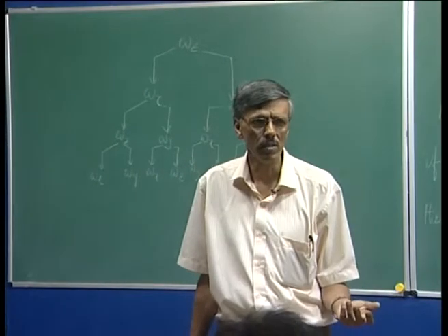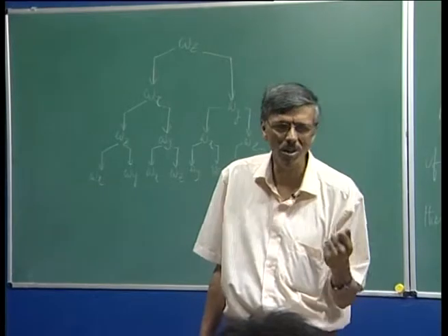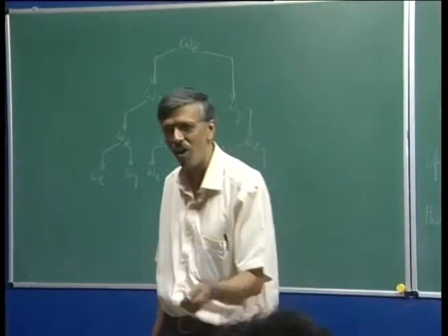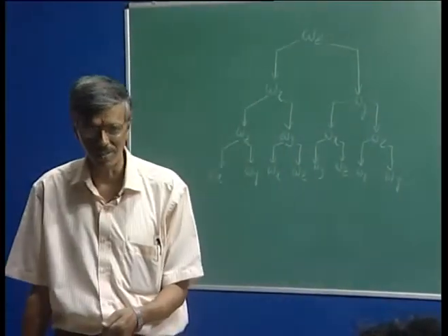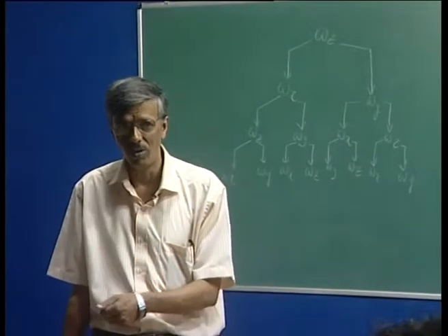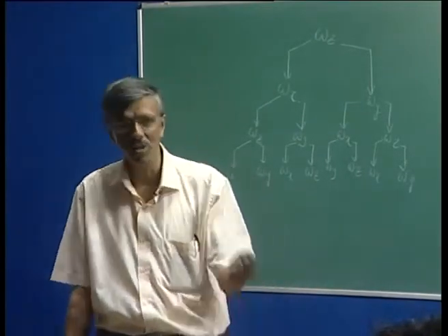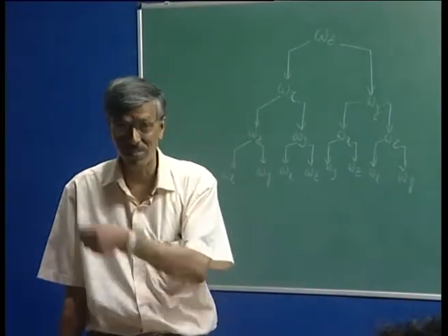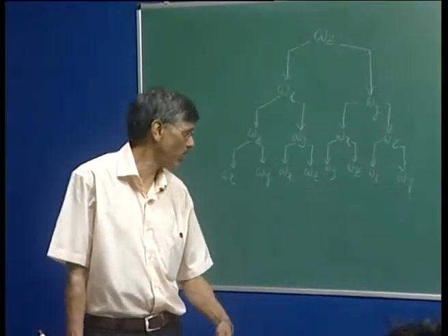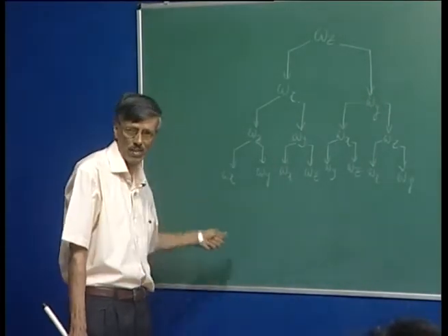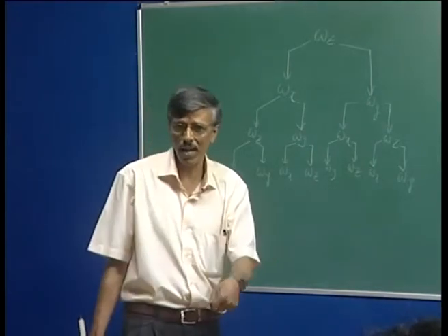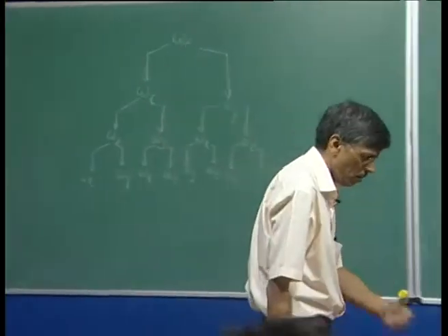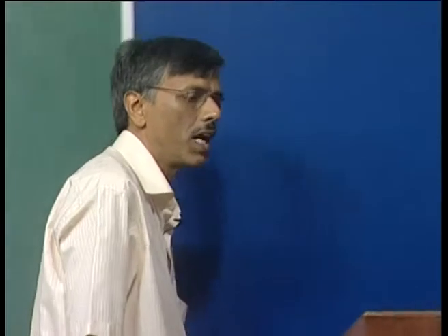And if this is not resolved in your computation, then you can model it, because now you are armed with that additional information that this is isotropic. See, basically modeling is always helped once you know what is happening. For example, previously we saw in case of time averaged equation how Reynolds stress was correlated with the mean strain rate, and that helped us develop turbulence model. So, in LES model also we make use of the fact that at the small scale, at the subgrid scale, we have isotropy. That is a very hopeful sign and good news.